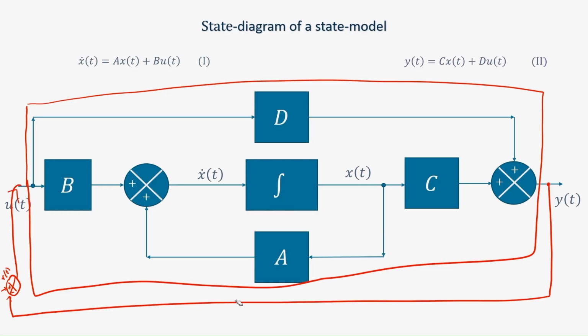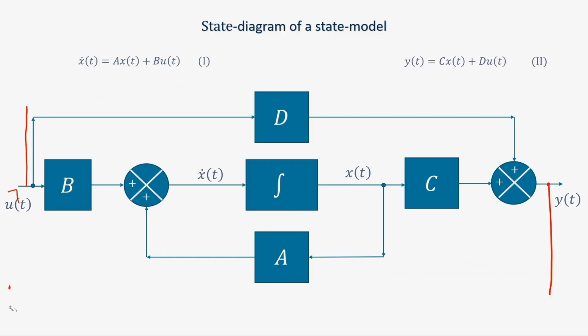You will see that in this case we will not be using that, we will be using something called state feedback, and I will come back to this diagram again when we discuss controller design for this system. Now, let us go ahead and look into the solution of x dot equal to Ax plus Bu.